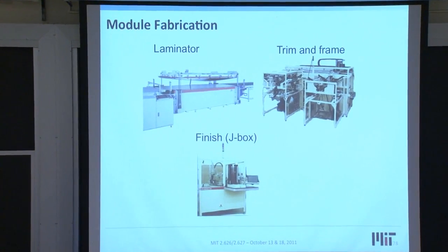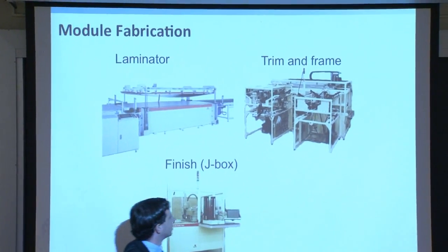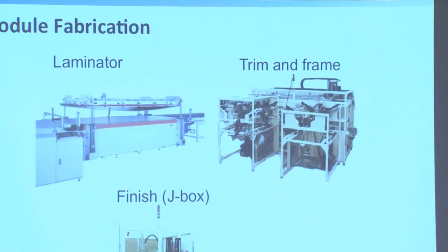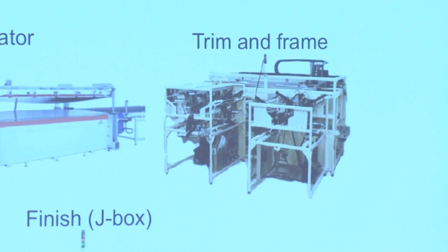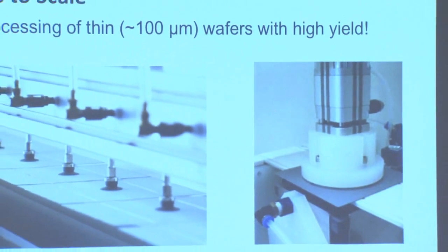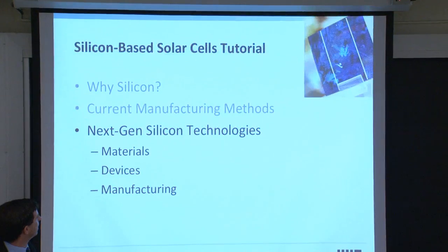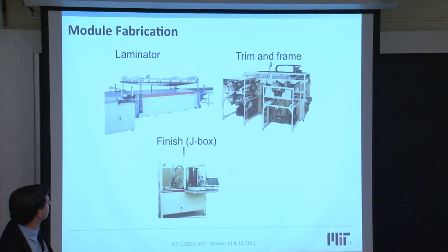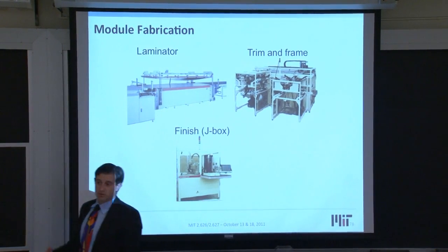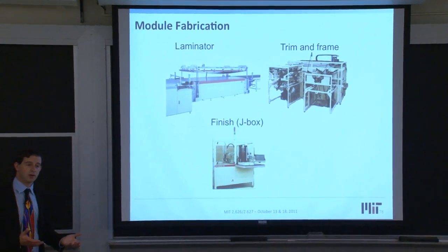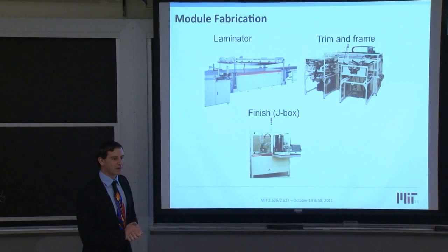And so to put that frame, we would need essentially a large machine that takes those pieces of extruded aluminum and pushes them together around the edges of the laminate, fixing them on there. And this is the examples of the tabbing and stringing right there. And let's see. OK, so the framing materials right here are typically done by machines in places with high labor costs, and they're done by human beings pushing them together at regions of low labor cost.